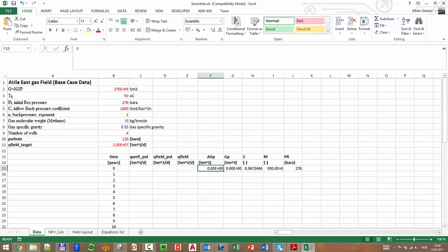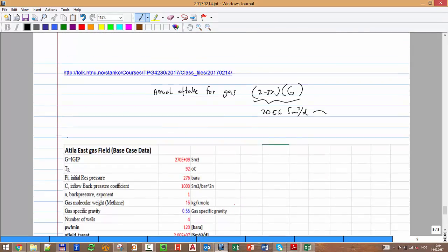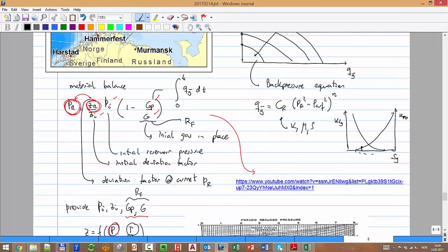But now I want to calculate how much my well can produce. For that, the reservoir simulator does it, and just pay attention to this part, in the following way. The reservoir simulator says, you gave me two values: the value that you want and the minimum value that you require to flow. So what I'm going to do first is put the minimum pressure that you gave me into that equation, and calculate the maximum that you can produce.